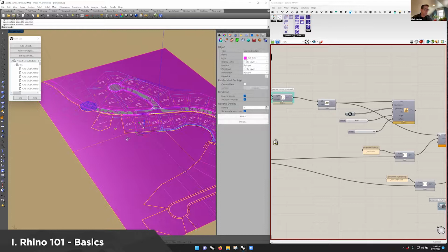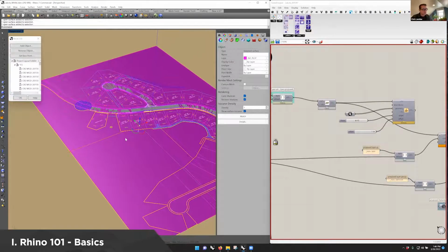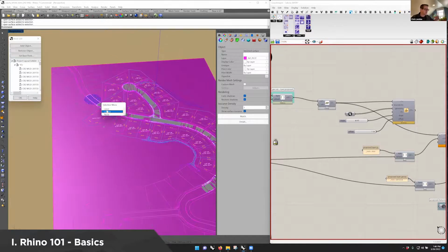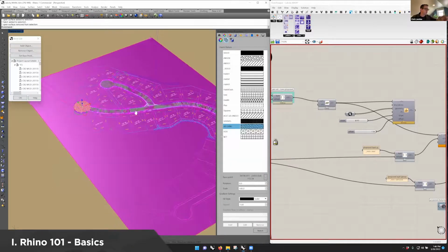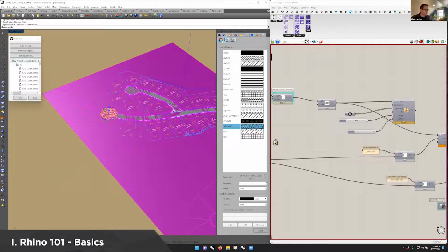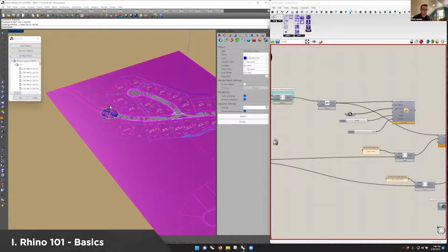The other thing you can do, if there are certain geometries that aren't working right and exist as a hatch, is turn those into solid hatches. If you select the hatch and go over to the properties, you can make it a solid hatch, and then you can explode the hatch and it becomes a surface, which is great.